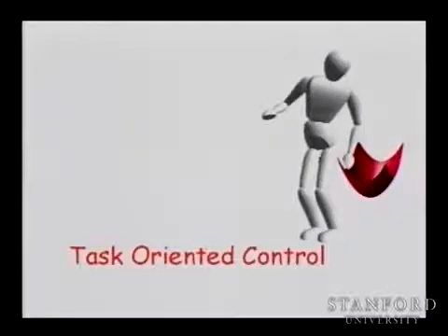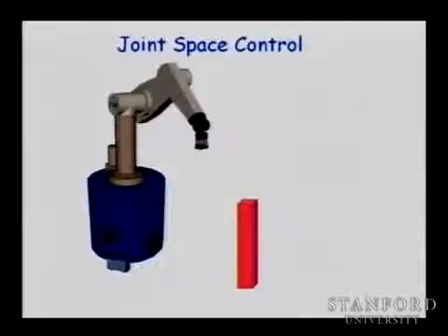And this brings the problem of inverse kinematics that you need to use to transform your task description in terms of joint trajectories. Well, this brings us to task-oriented control, where instead of thinking about the inverse kinematics as a way to transform the trajectories, we go directly to controlling the task. And I talked about this earlier, but let's take a simple example to illustrate this problem.